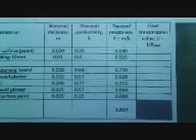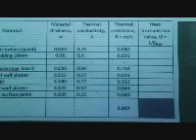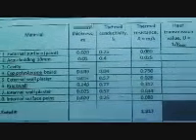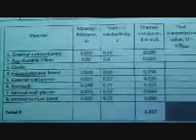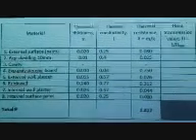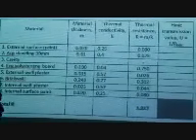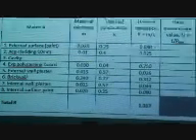Then we need to calculate the thermal resistance. R equals M divided by K, where M is the thickness of the material and K is the thermal conductivity. After doing the calculation, the total R that we got is 1.317.